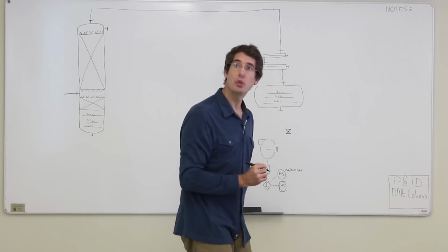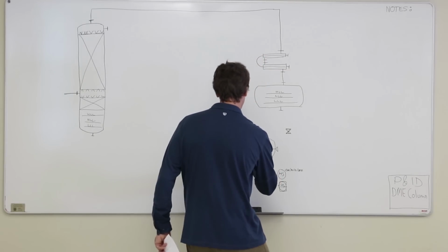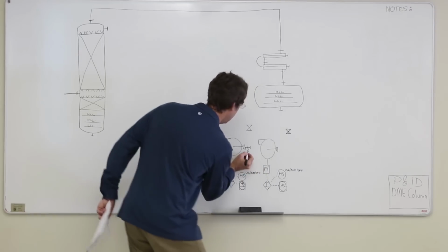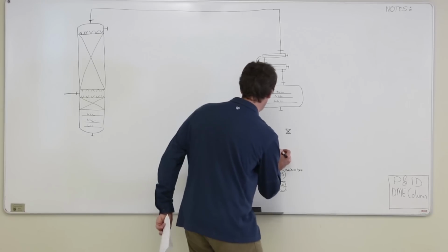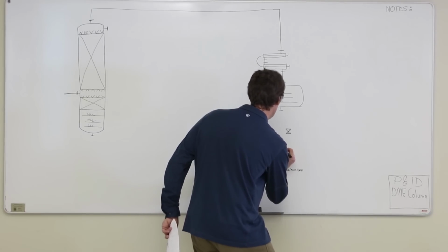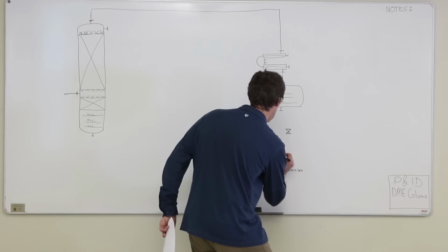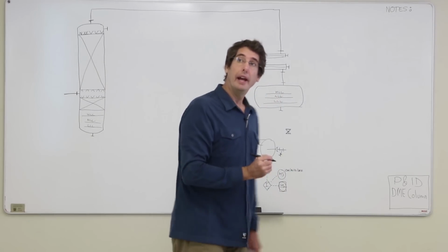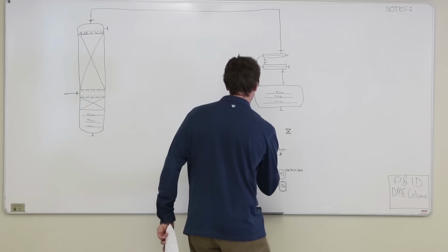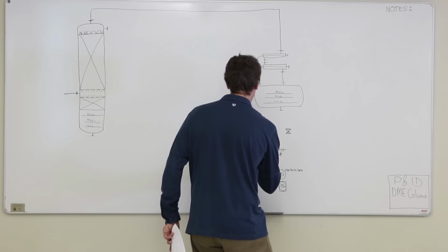And I'm just going to work backwards here. We need a strainer. So this is a Y strainer. And usually there's a small valve on there that you can drain stuff out with as well. The Y strainer just keeps the lunch boxes and the screwdrivers out of the pump. Small solids just go right through the Y strainers. They're really just there to protect the pump. And so if I put a drain on the Y strainer, I may not need one in the actual piping.